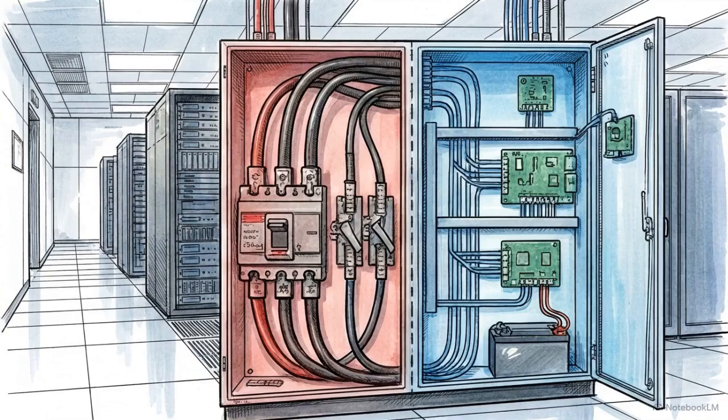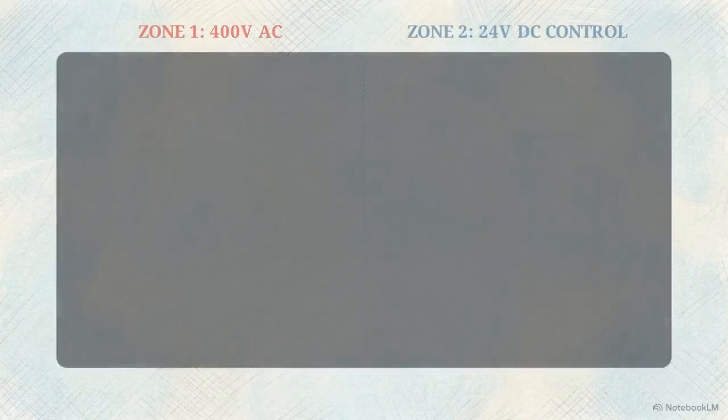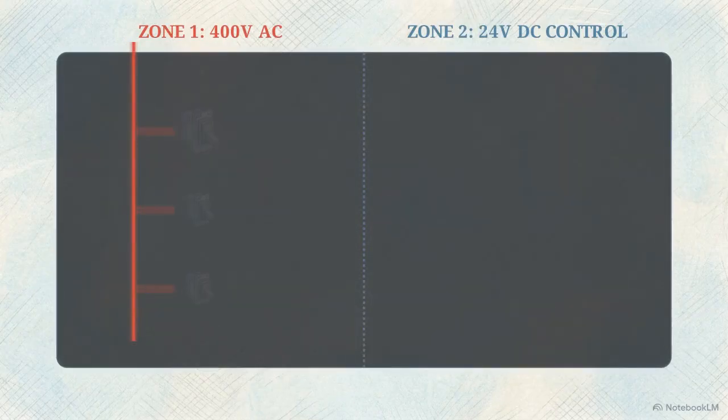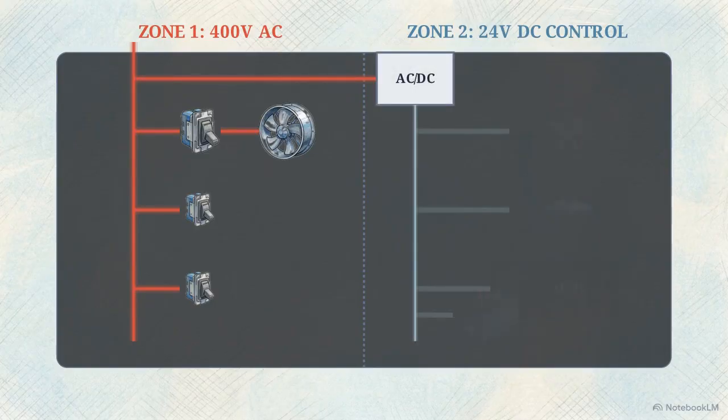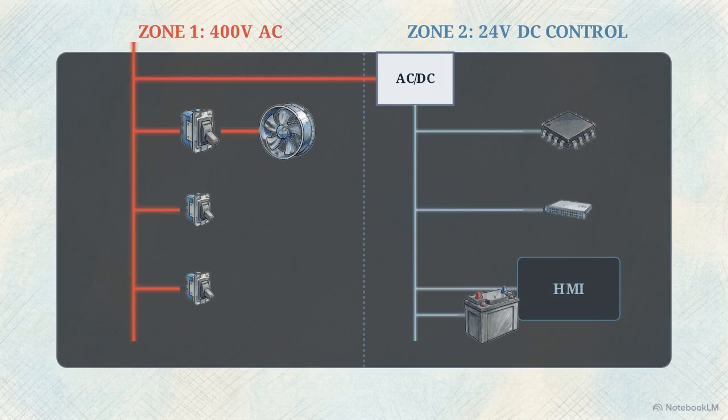Protecting this monitoring system from electrical faults requires strict geometric and electrical segregation inside the cabinet. The incoming 400-volt AC power is strictly divided. Zone 1 contains the auxiliary branches. These individual circuits run through miniature circuit breakers to feed mechanical systems like the room cooling interfaces and fire suppression panel. In Zone 2, a portion of that AC power is regulated to create the 24-volt DC bus.